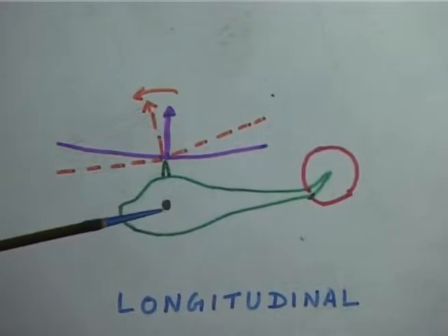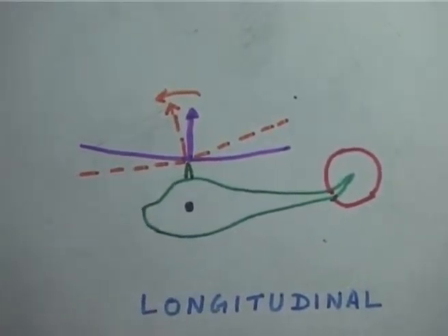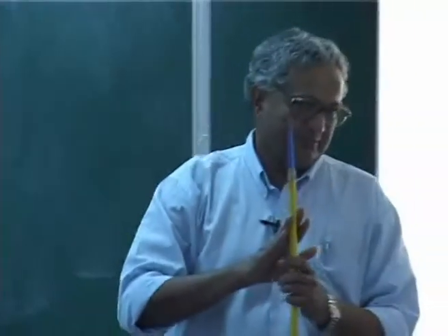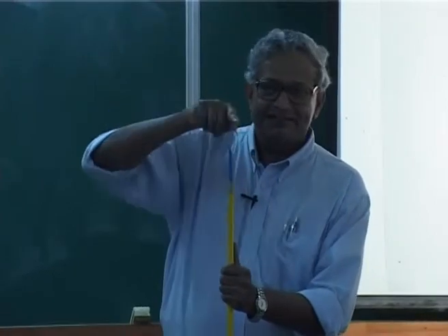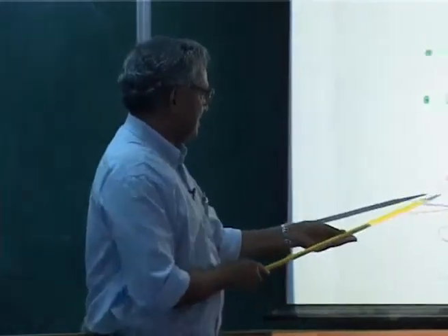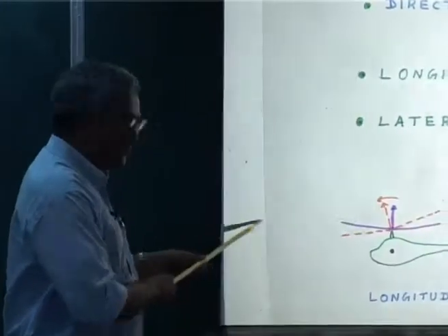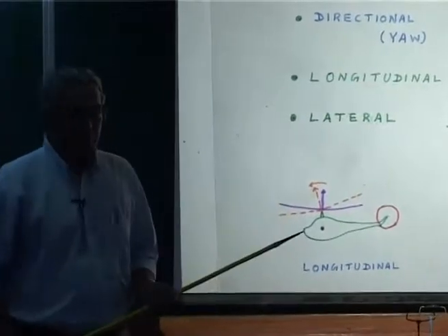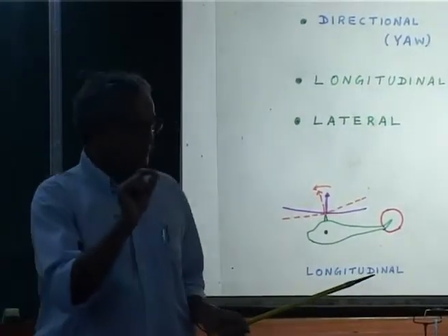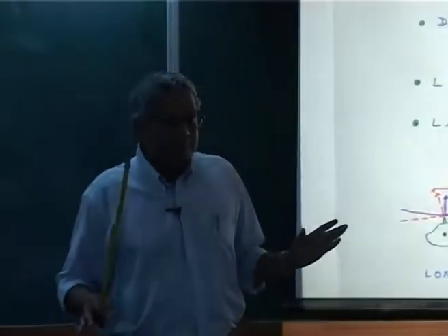and when he gives longitudinal, the disc may tilt with respect to the shaft. So, initially the disc is like this, then it tilts. As a result, it develops a forward component of the rotor lift force, and that will move the helicopter forward, but that will also give a moment about the CG, therefore, it will pitch. So, these two you cannot decouple.